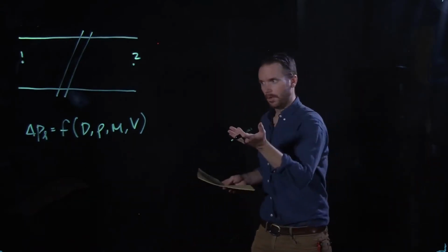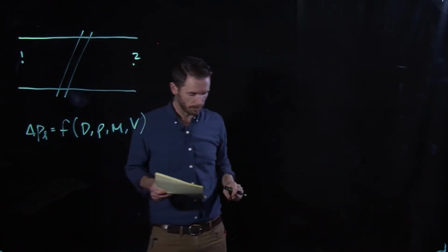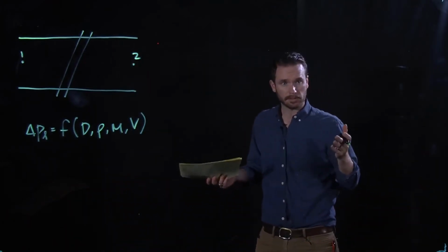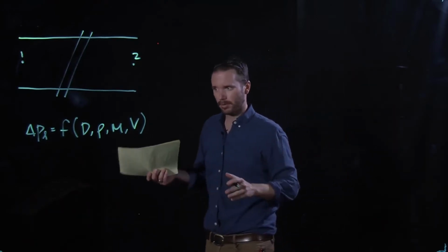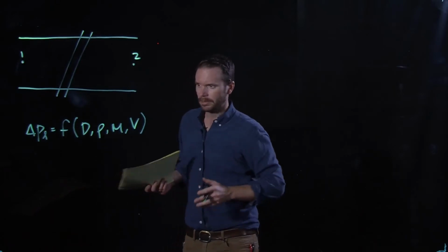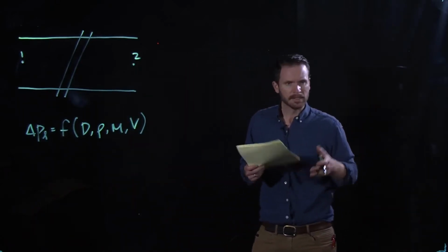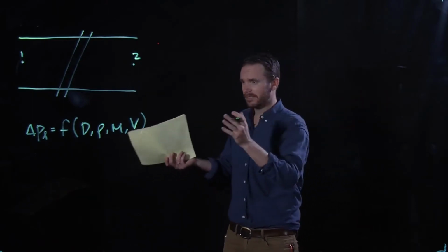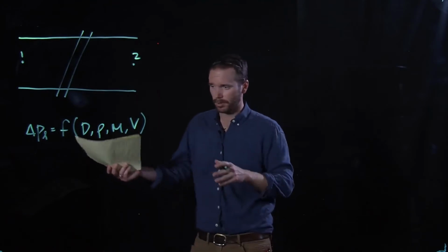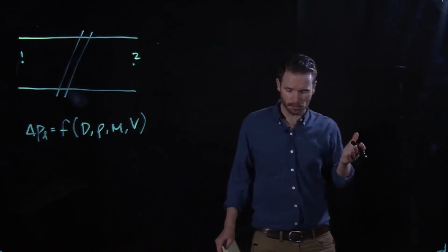All right. So we have this long, smooth pipe, and say we have a fluid flowing through it like water. And what we're trying to do is determine the pressure drop per unit length. And we've already discussed that that pressure drop can be affected by a number of different variables, right? We've chosen diameter, density, viscosity, and velocity here. And we talked about the fact that if I tried to design an experiment that captured all 5 of these variables, pressure drop plus these 4, it becomes quite difficult to have a proper control.